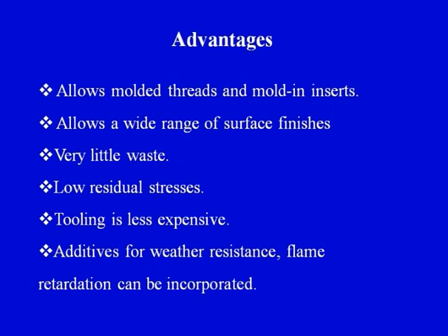So there can be a number of advantages that we can derive out of the rotational molding process. So we can see once again, let us revise. Molded threads and mold-in inserts can be easily incorporated in rotational molded products. Wide range of surface finish can be achieved because it depends upon the finish of the mold surface. Wastage is minimum. Residual stresses are also less in the rotational molded parts. Tooling is not very expensive. Also we can incorporate flame retardancy and weather resistant additives in the raw material, so that the product that we get can be used for these specific requirements.